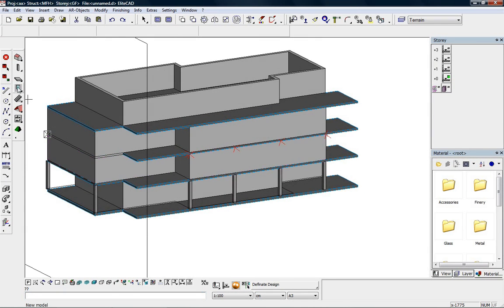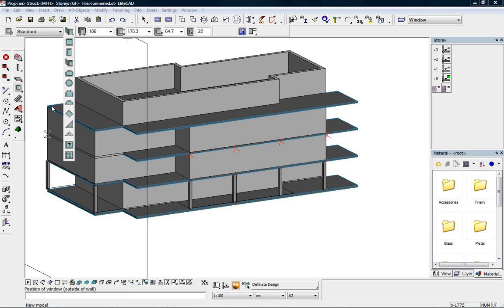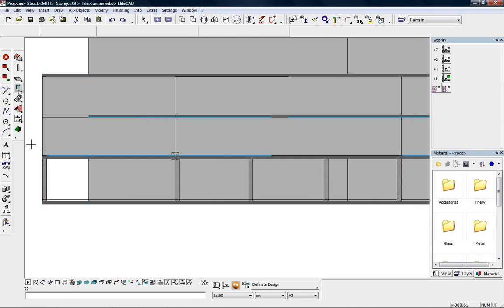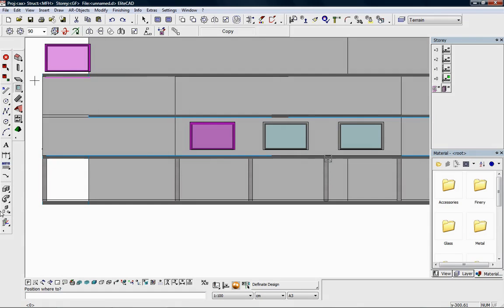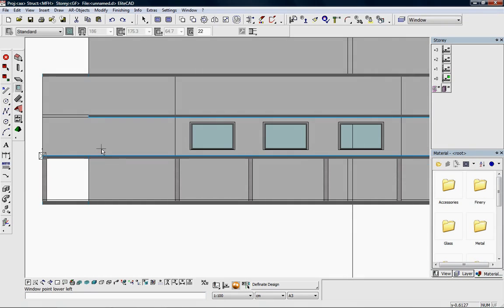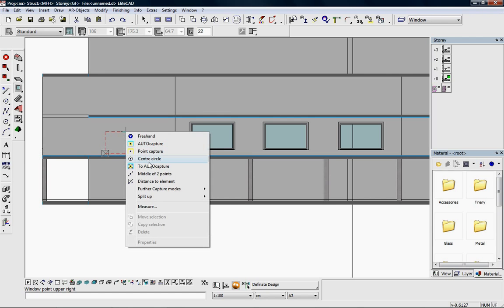We can also create openings directly into the model, for example, a window that extends over multiple floors. We turn the view so that we can add another window directly into the facade. The windows can, for example, be created by stretching a polygon over the desired location. Although there are precise underlying measurements involved, the program allows for a simple interactive manipulation.